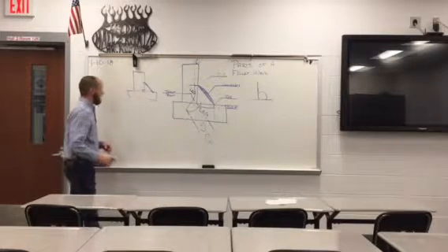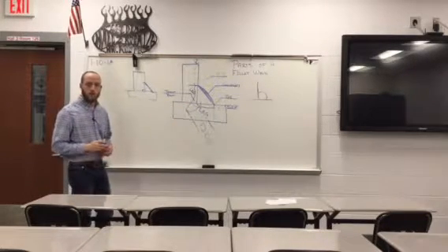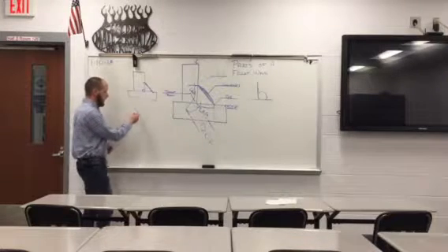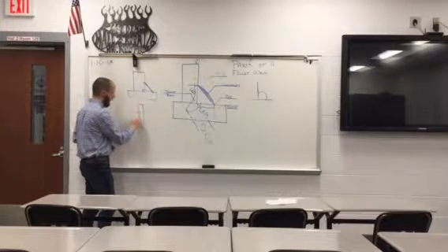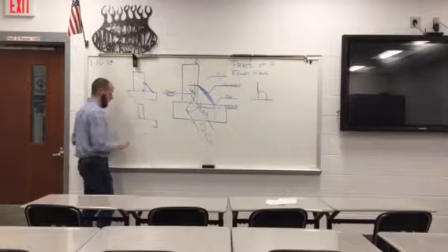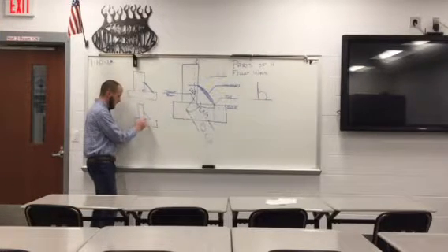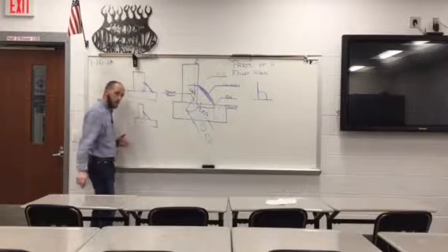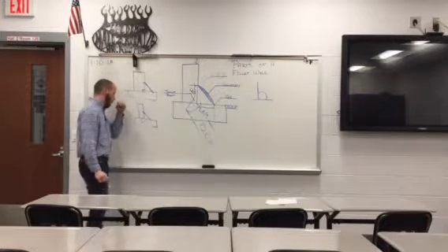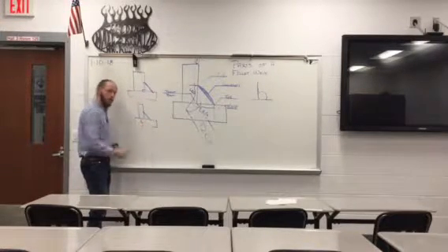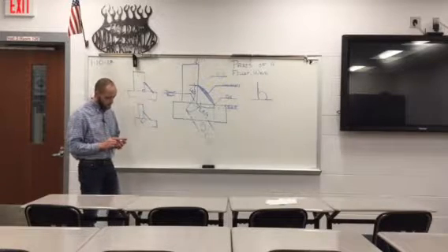Like I said, it's very seldom referred to, but the next one is more used than the theoretical throat. It's the effective throat, measured from the face of the weld without weld convexity through the depth of penetration.